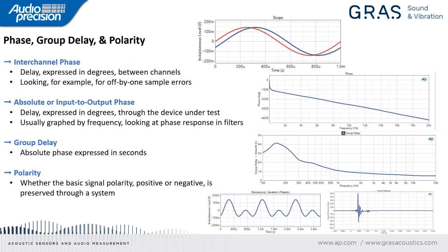The final thing I'll touch on vis-a-vis phase is polarity. So we're talking about an AC signal when we talk about audio, and the question is, if you inject a positive going waveform into the device, does a positive going waveform come out of the device? And in the case of, for example, a speaker, you can just reverse the voltage terminals. Now, polarity is not normally important unless you accidentally reverse it. So for example, if you have a headphone and the polarity is reversed on one of the ears, that will sound terrible to a human listener.